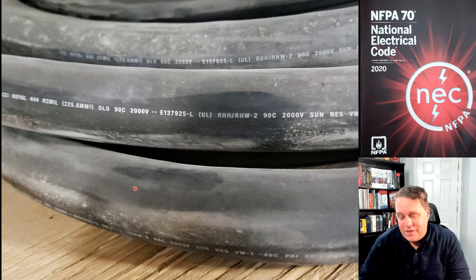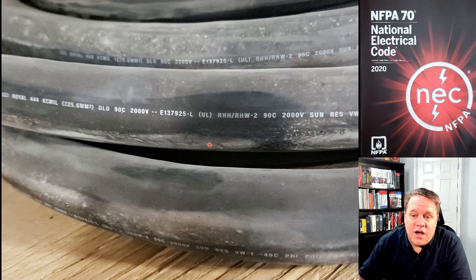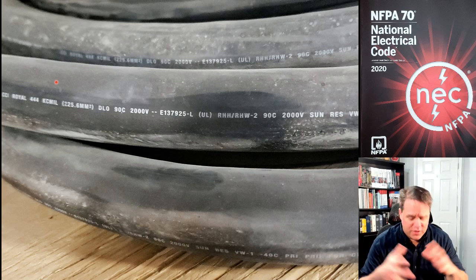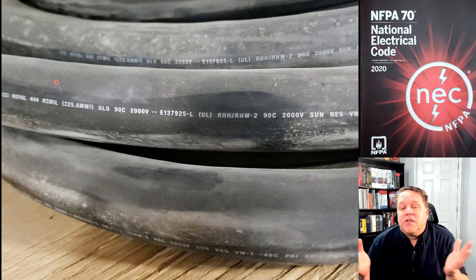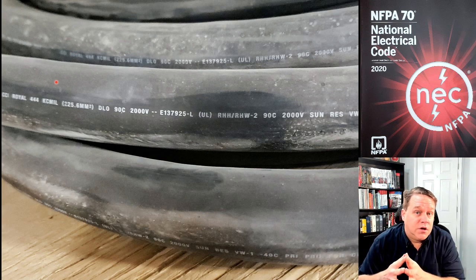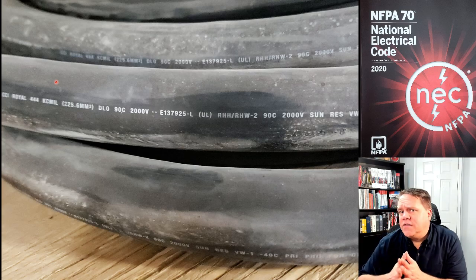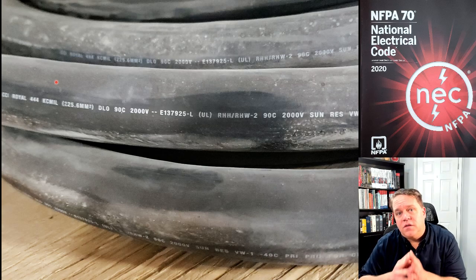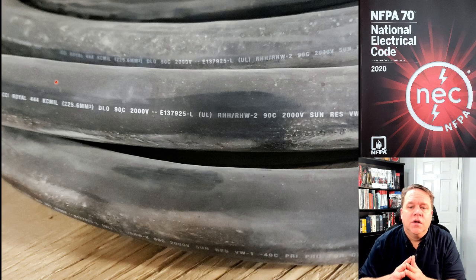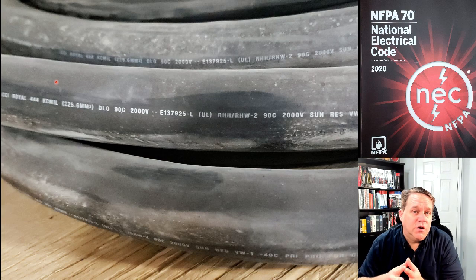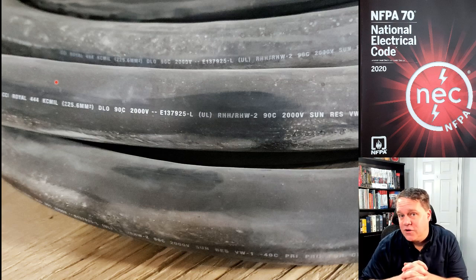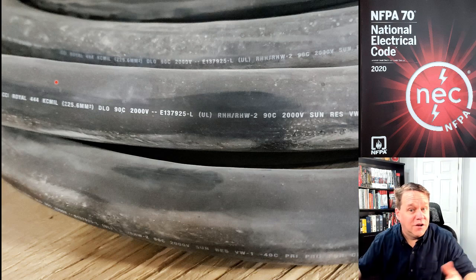And of course they'd freak, and I'd say, all right, let's keep looking, and if it says RHH/RHW-2, then you can put it in. Now that still begs the question, what's the ampacity? And until the 2020 code, that wasn't addressed. It didn't give us any guidance in the 2017 and previous versions of the code to tell us what to do. Now in section 310.15, it actually says for ampacities that are not indicated in table 310.16 or 310.17, then the ampacity can be interpolated using engineering supervision. So get yourself an engineer that can extrapolate the current between 450 and 400 kcmil and figure it out that way.